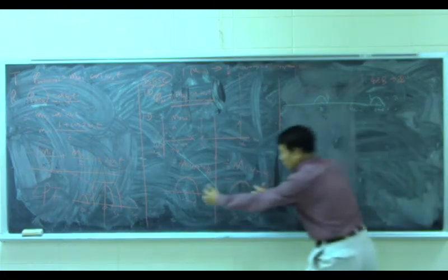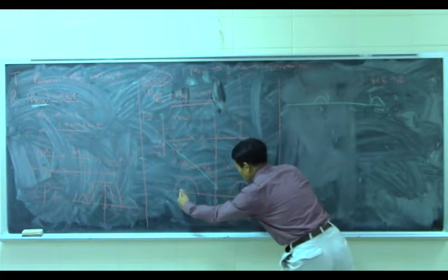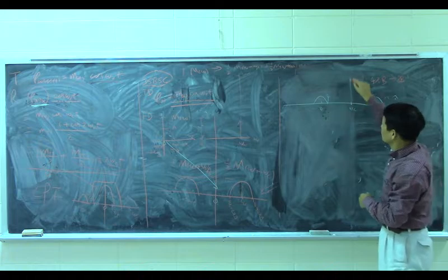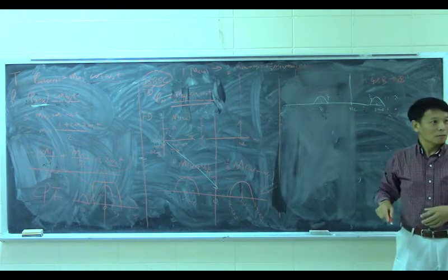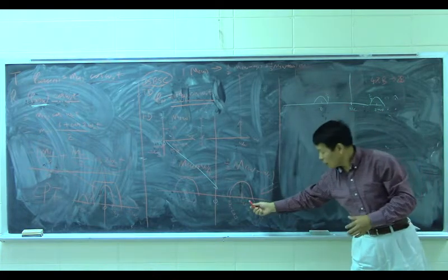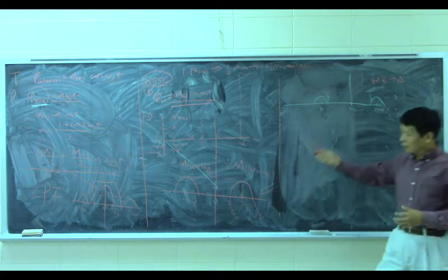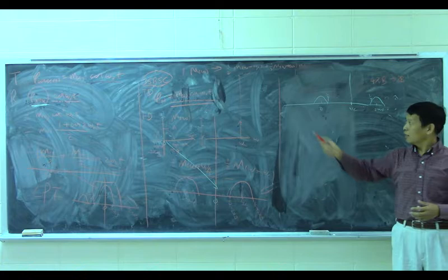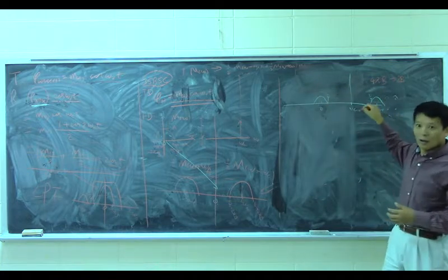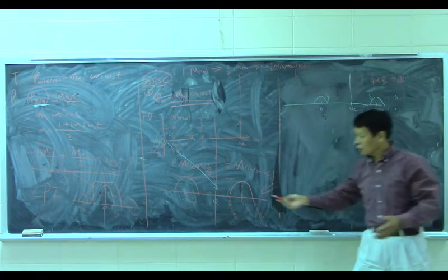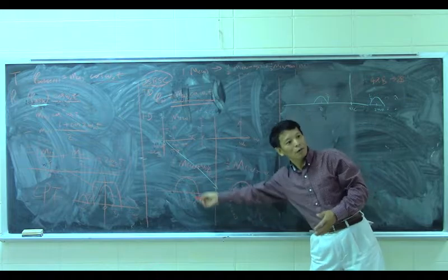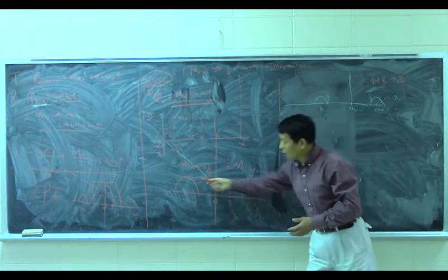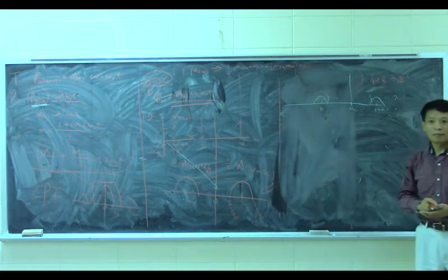So these two together from centered at 0, then to here, centered at omega c. Make sense? We have two parts, right? This part will be at 2 omega c. This part will be at 0. And these two only shifted to the right from here, and you reduce the amplitude from half to a quarter.